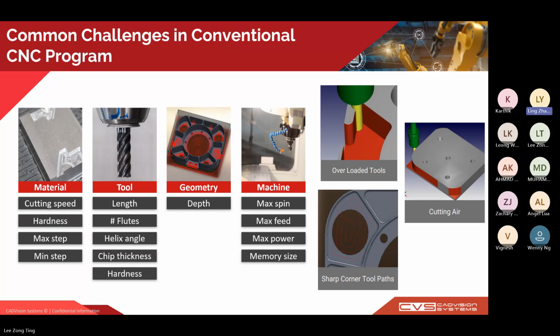Maybe when I'm cutting a sharp radius, only 30 or 40% of my tool is in engagement with the material. So this will create an unbalanced force and result in significant differences in cutting forces. And also, to avoid tool breakage or wear, operators are forced to slow down the feed rate and take a relatively shallow cut, not because the whole part requires it, but just to handle those few high-stress areas.